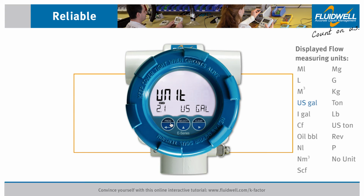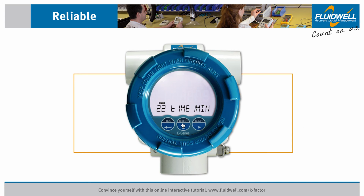Go to Menu 2.2 Time. In this menu, you can change the time base unit for the displayed flow rate. Press Prog to change this setting. We are going to select the seconds value. Press Prog to store this setting. The time base unit for flow rate is now set for seconds. The next step is to set the decimals for the displayed flow rate.